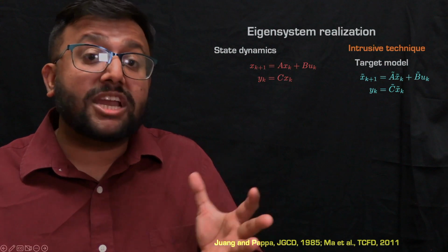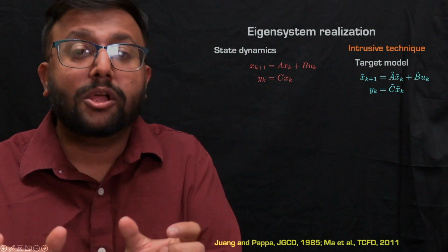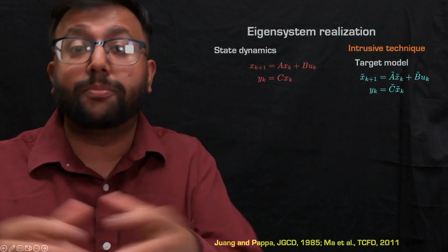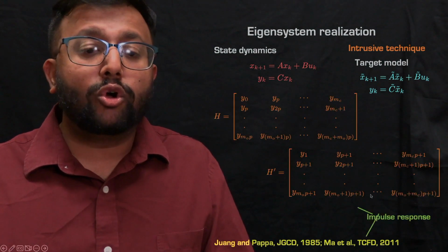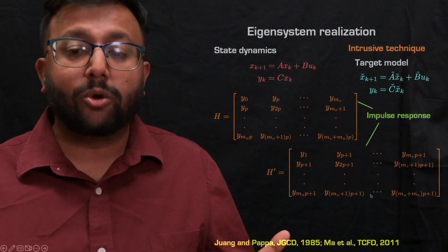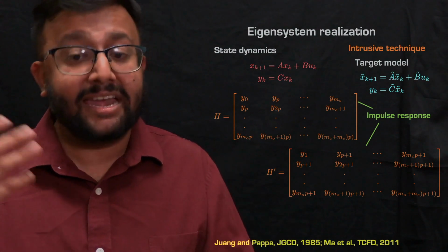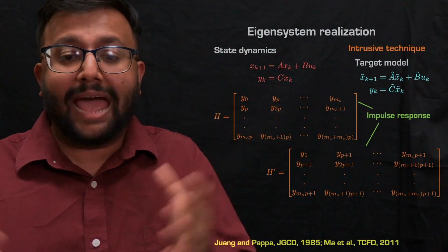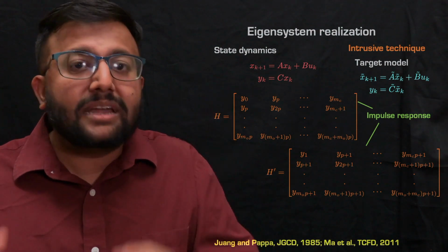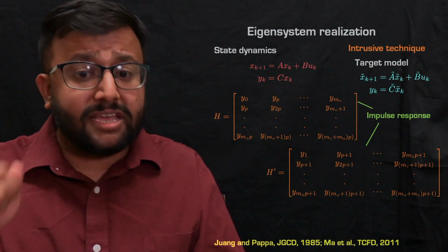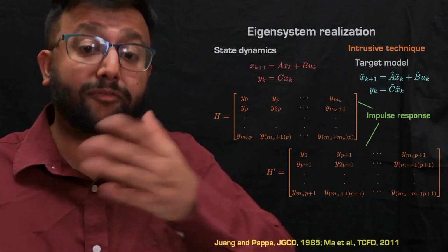So in conclusion, for this system, we want to basically maintain the input-output relationship in the system dynamics of the reduced order model. To build this reduced order model, we are going to build two Hankel matrices, H and H prime. Now, H and H prime can be thought of as time-shifted matrices, just like in the DMD case. So it's built the exact same way, but the entries of this Hankel matrix are going to come from impulse response studies performed on the original system.